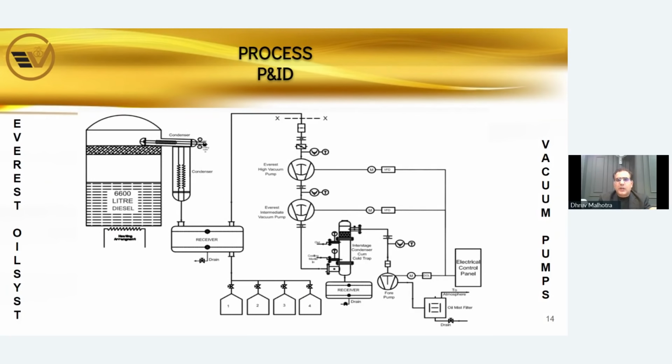Because this is a high boiler, vacuum is connected into the receiver. As we are very well aware, there will be no further carryover of vapor by connecting into the receiver into the vacuum pumps. Typically, we promote and tell customers to always connect vacuum in the condenser and maintain the condenser as the lowest vacuum point in the whole circuit.